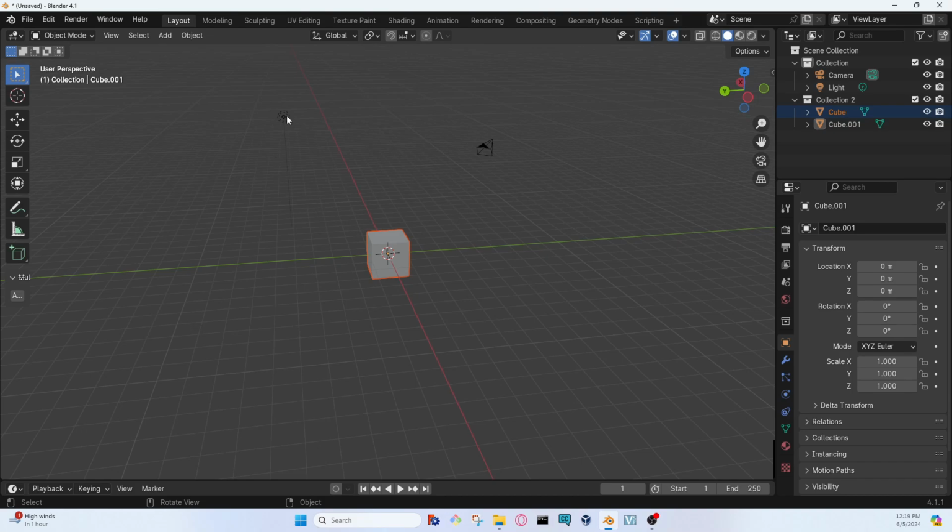That way, whether you're doing lighting or you're doing camera rendering, if you're trying to find the camera and your scene's gotten really big, you don't have to dig through one big collection. You can just straight go to your top collection, which has the camera and whatever lights you have, and you just snap to them by hitting the decimal key, as long as you have the cursor inside the viewport.